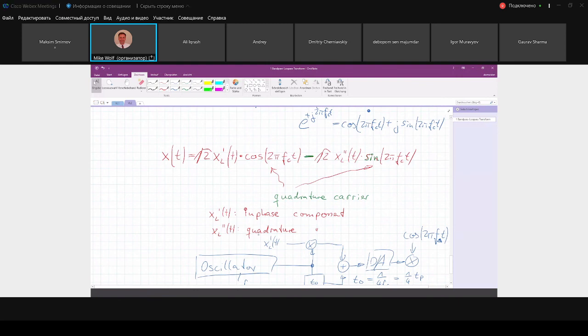And separately, I obtain the quadrature component by this analog circuit. And then if I just draw a figure here on my board, I can say, now I take this and add plus j times this. But this cannot be realized in the analog. What I've shown in the figure is the real world. This is realized by schematics in the analog domain.